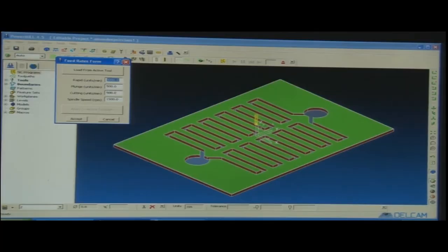For instance, if we use rapid speed, from a far off distance the tool can come closer to the workpiece at rapid speed, and then it can start machining. So, this rapid speed would save time, and this is very important. We need to put some values here. The rapid is the speed, so many units per minute. How rapidly would it come close to the block and start machining? So, rapid is 3000 per minute, and plunging is actually the final machining.